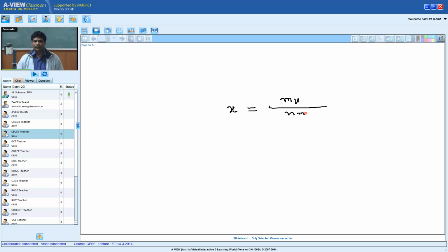Now what is the meaning of total mass of the mixture? Obviously this will have the mass of a fluid, generally the standard for liquid, plus the mass of vapor. The f stands for liquid mass. So this is what is called x. What is internationally agreed is, number one, it should be a mass fraction, not the volume fraction.